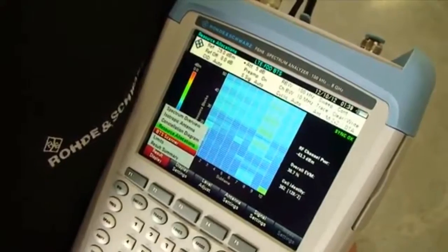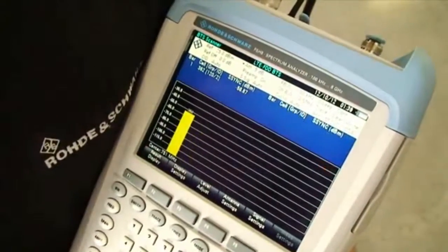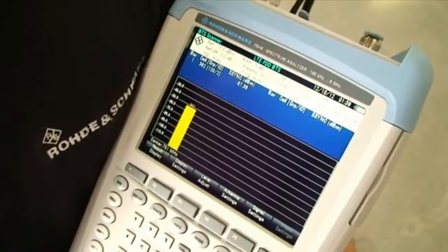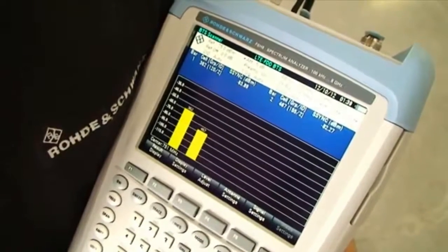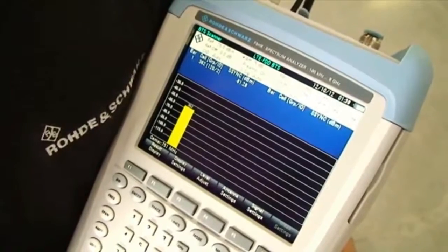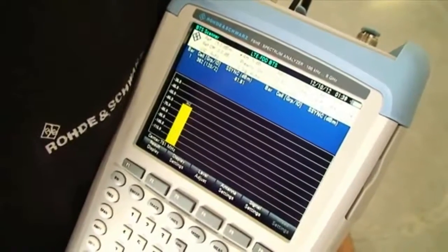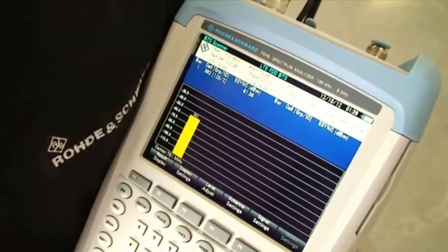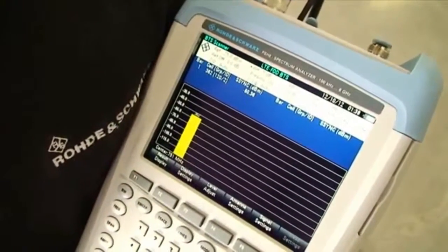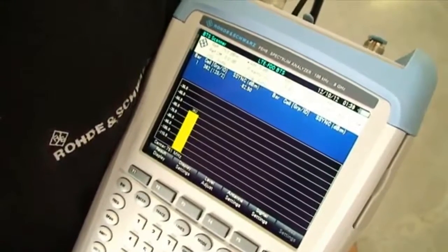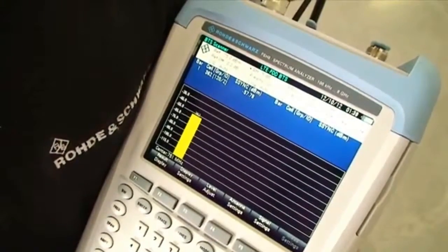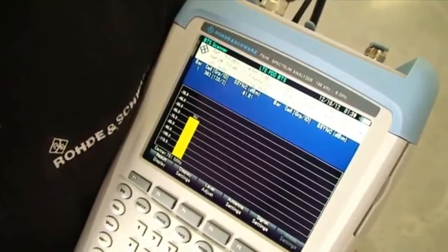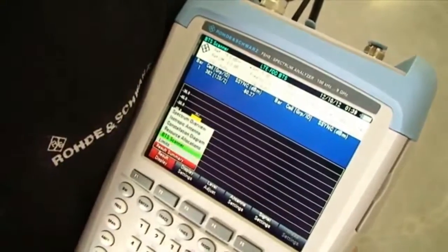Lastly, I'll show you the BTS scanner. In this very simple view, we just show cell IDs to figure out which towers are in the area and broadcasting LTE. In this case I see 362. Sometimes another sector may pop up as 361 or 360. This is expected. But if I see another tower such as 78, that doesn't make a whole lot of sense, and that may be my first line of defense to figure out whether we have some interference going on. So the FSH is a really good tool to do demodulation over the air, and these are just a few of the tools that the FSH is capable of.